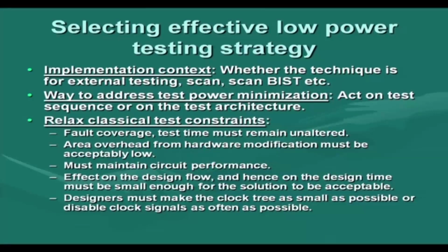If we do not apply those patterns, certain faults are not covered, so fault coverage will get affected, but still it may be acceptable because the power consumption is less. The test time may change, but fault coverage normally is not traded off.